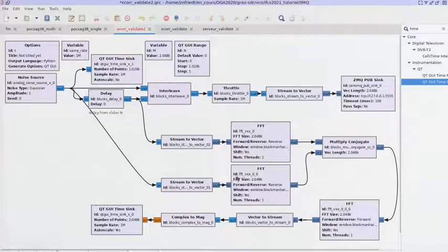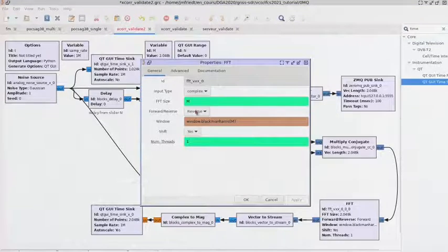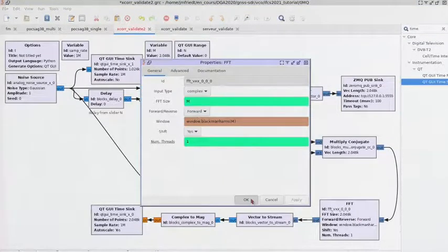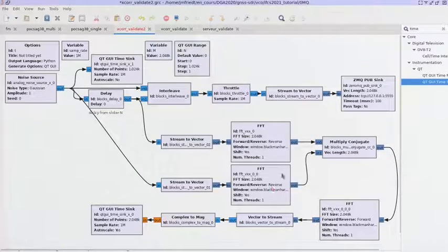Now actually notice that we take first the reverse Fourier transforms and then the forward Fourier transform. This is just a matter of convention as to where the zero is located, if it's on the side or on the center of the Fourier transform. This trick allows us to have the center frequency at the zero delay.